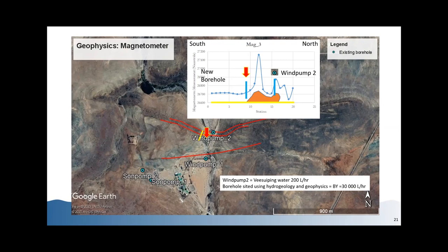And you want to site on the up gradient side of the dike because the center of that dike is impermeable. So it essentially acts like a dam wall. If you site on the down gradient side of the dike, you're going to have far less water to no water than on the up gradient side of the dike.